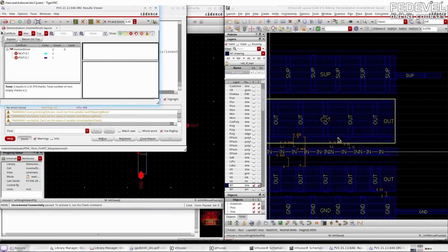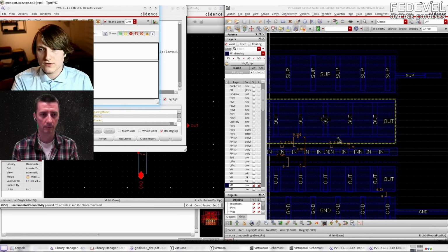But you would do this for the entire cell. And when you're done with that, you would then do what we call a layout versus schematic. In PCB tools, this is often integrated. It's a thing that checks for shorts and opens, and makes sure that everything you have connected in the schematic is actually connected like that in the layout, because this gets quite complicated. Sometimes it's very easy to make mistakes.